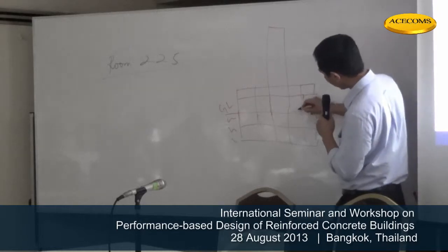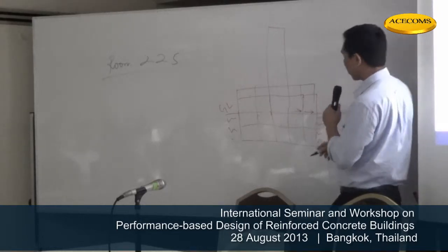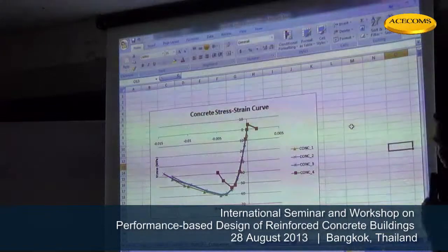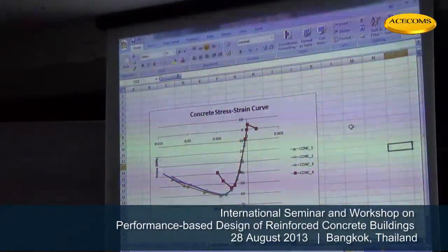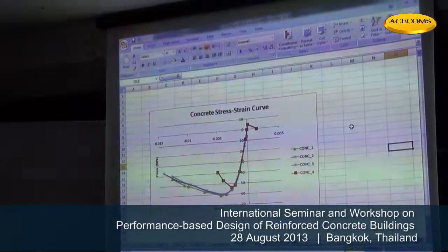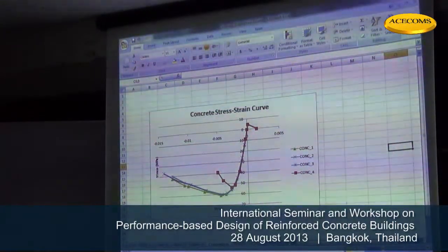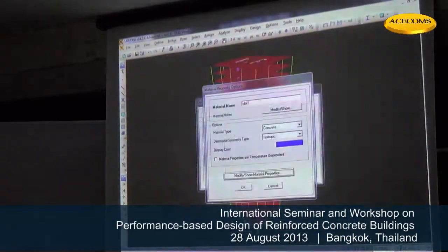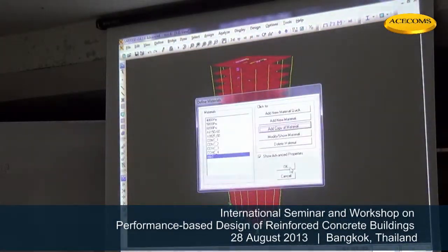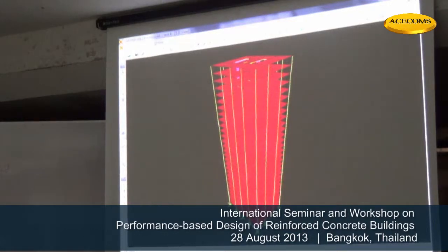So in this load path, there will be a lot of in-plane stresses in the slabs of the ground floor level and basement levels. Not only that, at this sudden change there will also be significant force transfer from the tower to the podium level frames. So we have to take care of the diaphragm design.